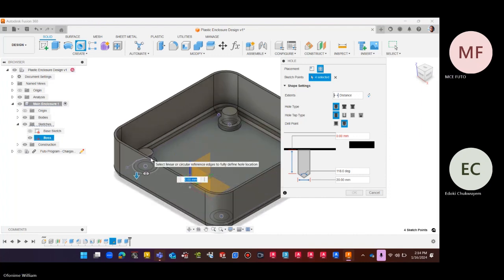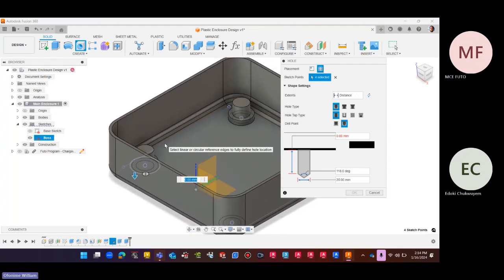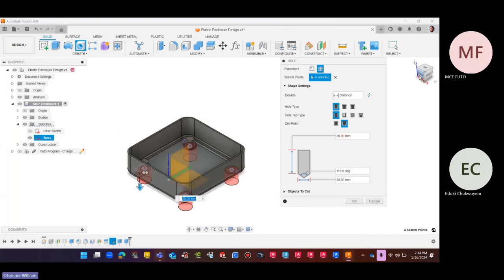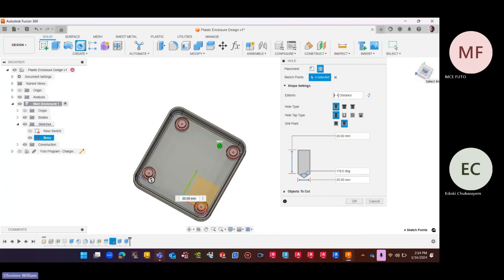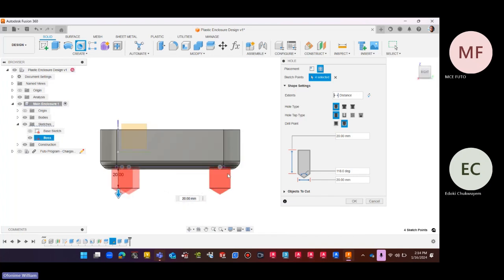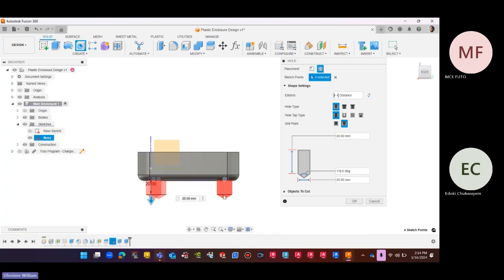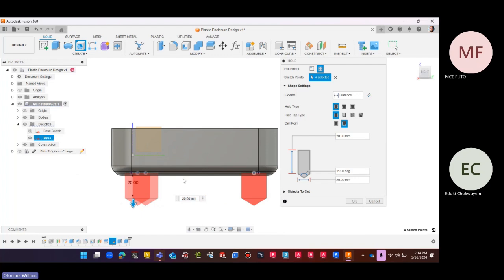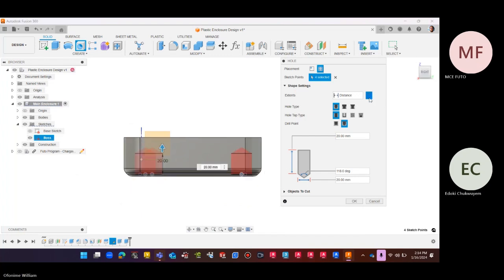But what we are going to do now, if you notice, is going down. Can you see? And that's because the sketch is under. So you're drilling a hole just as you do on your milling machine. The direction is coming from here, it's just assuming that you're pulling that hole down. Forget about the size, we'll correct that, but the direction first is not correct, and a simple flip will not get it done. I'm just doing that to show you.